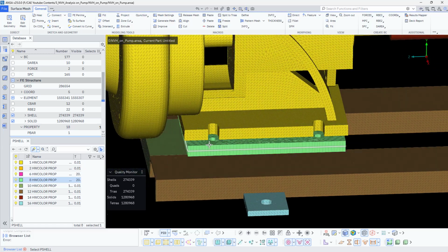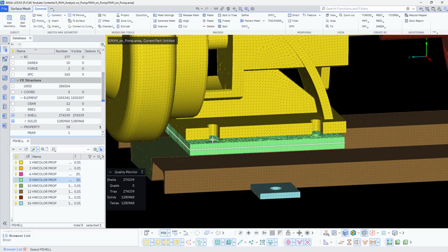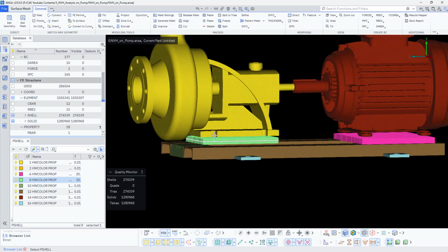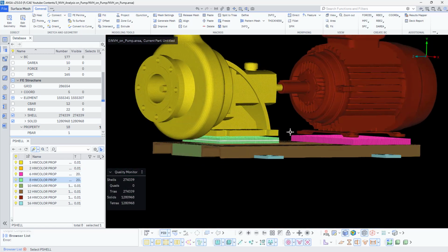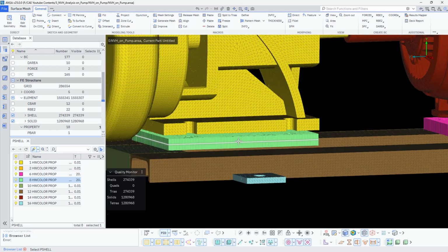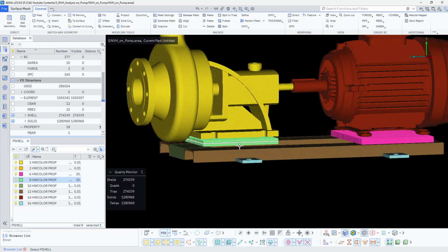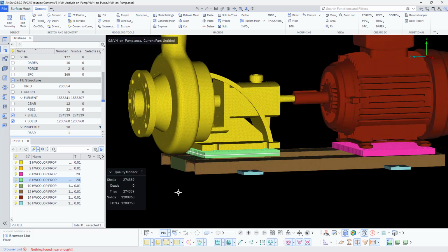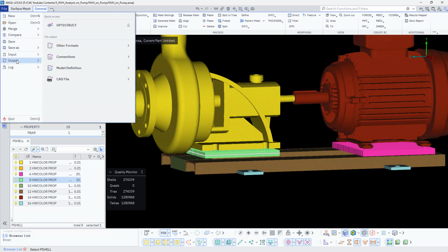Initially it was 30. I reduced it to 5 mm because I wanted to see whether reducing it to 5 mm is going to impact the stiffness of the model, or whether it is working fine or not. But I could see there are huge peaks and drops. So in 5 mm thickness I can't make it. So what I have done is I have changed it to 20 instead of 5 now.